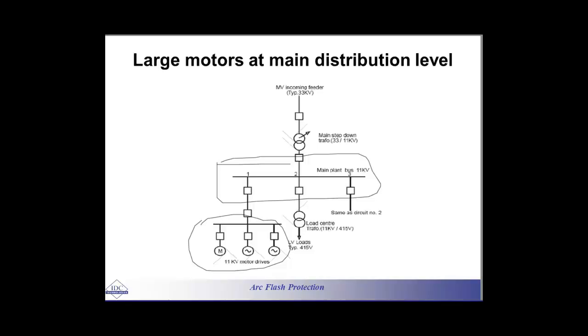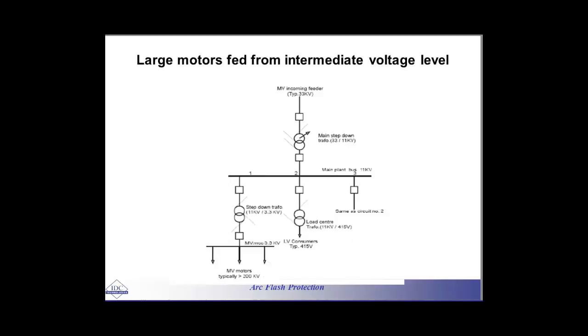So these motors, so what happens is that, and as you can see in here, we have got a standby generator in here. So the problem is the start up of the motors, for which you need to be very, very careful. Otherwise, you might have some voltage drop on this 11 kV bus, and as a result of that, the circuit breakers may be tripped, and you would lose the supply to your load center in here. So in starting up these motors, you have to be very, very careful, right?